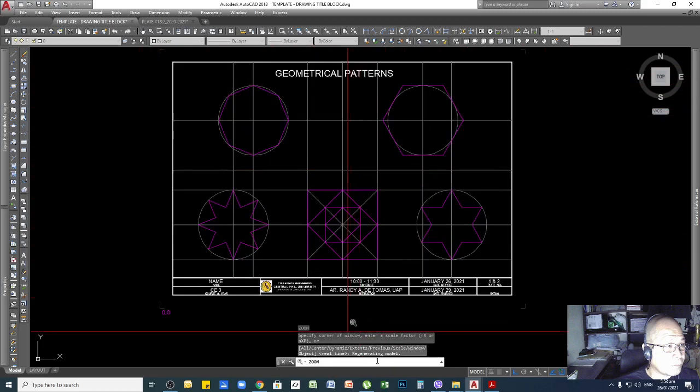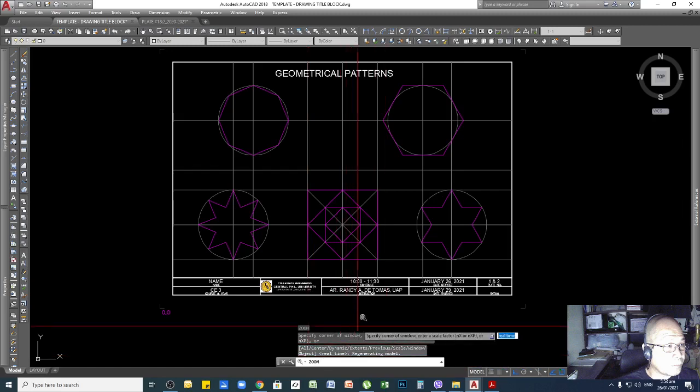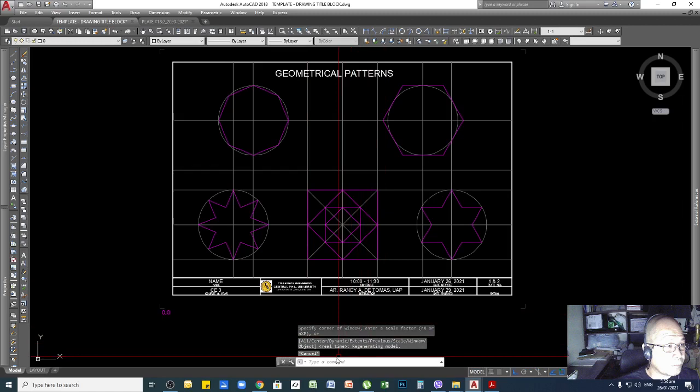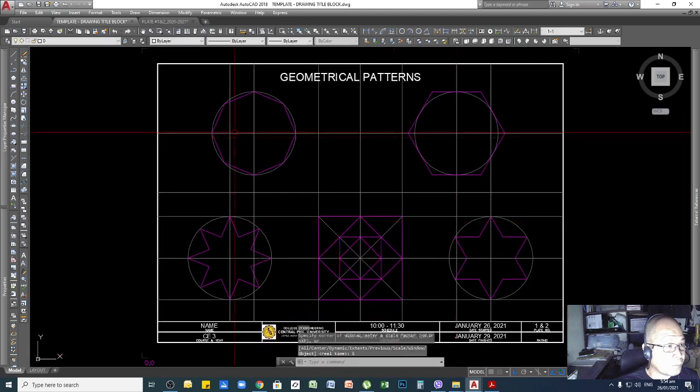So all you need to do is look for that portion. Let me go back again to zoom command. I will cancel this. Zoom, enter. There is a selection there that extends. So extends means whatever are the objects that you've done in your screen, it will show. So I will select extend now. So by typing E, so you see it sets to the limit.